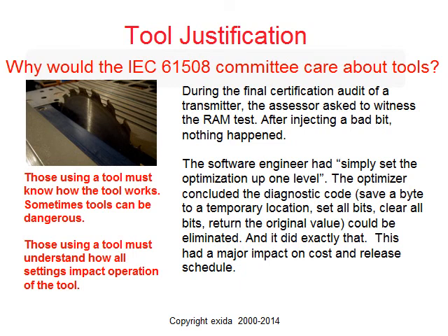Well, in digging into what happened, why that didn't work, why this product that had previously worked and had good diagnostic coverage didn't work, it was found that the software engineer had simply set the optimization level up one level. The optimizer concluded that the diagnostic code, for example, save a byte to a temporary location, set all bits, clear all bits, return the original value, could be eliminated. It did exactly that. So one, it made the diagnostics not work because the code was gone, and it meant that this OEM had to go back through and redo a fair part of that project with the compiler with the proper setting and redo the validation testing.